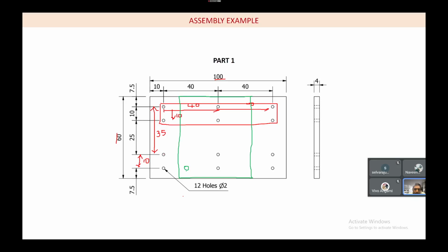So yes, this will be 20. Which means that if I go to this exploded assembly, this distance is going to be 20 mm. So now I know where to place this sleeve. Let us now place it. First of all we will do the constraining. We shall first mate this axis and this axis. So now they are exactly placed.